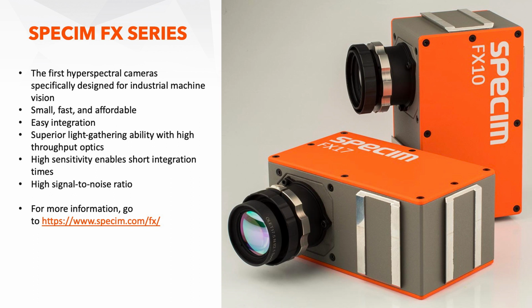Also, we paid real attention to the F-numbers so that the light gathered by the camera is collected efficiently, so that the customer can use them with a short integration time, fast acquisition rate, and a still affordable quantity of light, in order to use them with a good signal-to-noise ratio. It's what we call the high signal-to-noise ratio.